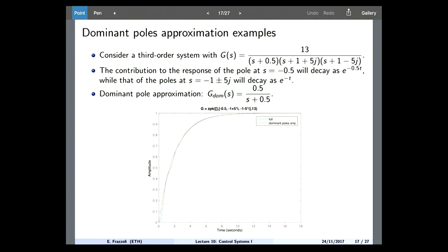So what was the question? No, because as I said earlier, we use the 2. So in this case, what you see is that the dominant pole is actually 1, and it's fine. Just remember that the specifications on a single pole are actually simpler, right? So you have no overshoot, and rise time and settling time are actually the same thing, right? Okay. Other questions?